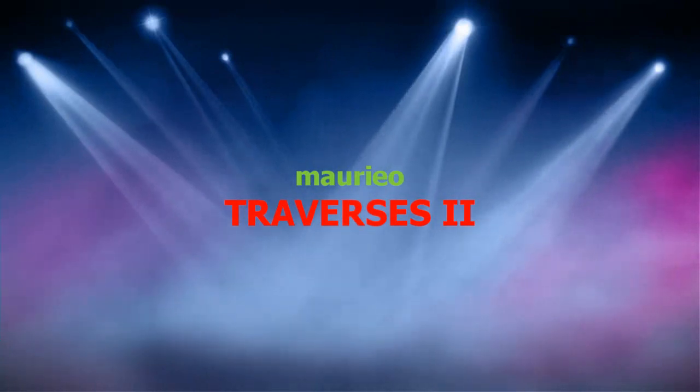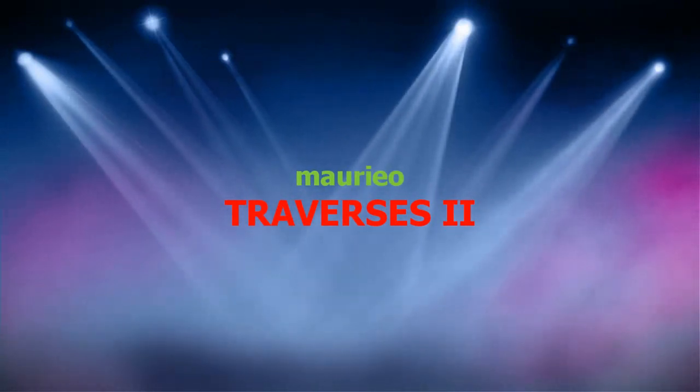This is another one of my videos where we're going to simulate a survey traverse situation, and this one's slightly different. So first of all, let's have a look at what we're going to do. We have a larger lot here, which we're going to split into two lots, lot 1 and 2, and we're going to make the boundary coincident with this fence line running through here. We have taken ties onto posts 1, 2 and 3.